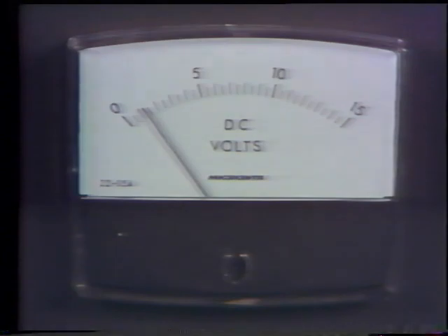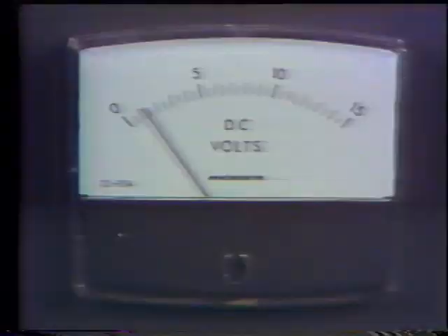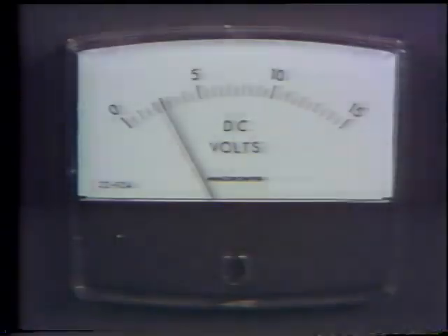Now let's use the voltmeter again to make sure that the voltage drop across each of these 3 resistors is in direct proportion to the resistance of that resistor. Okay, reading on R1 is 1 1/4 volts. We take a reading on R2. We also get 1 1/4 volts, and we have 2.5 volts left, so the voltage drop across R3 should be 2 1/2 volts, and it is. In each case, the voltage drop across a resistor is proportional to the resistance.